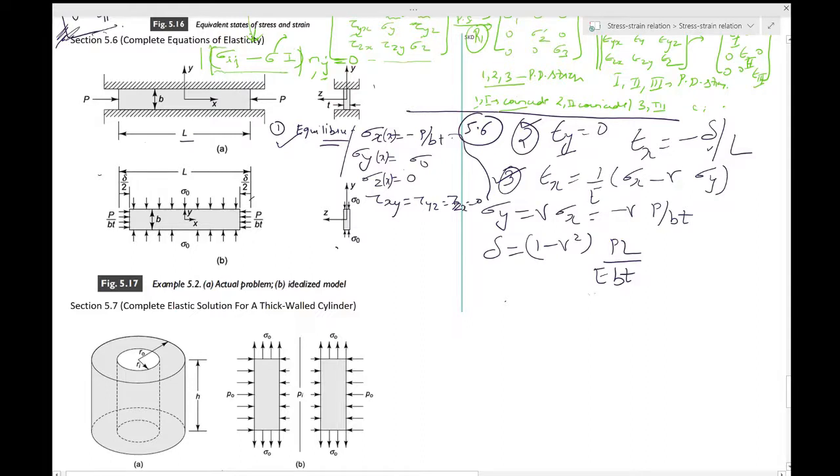Okay, and then you would have the strain in the z direction as nu by (1 minus nu) delta by L. So please verify this. Don't take it at face value. That way we can also check whether what the author has done in their textbook is correct. Please derive this and confirm. So these expressions are given in your book as equation E.